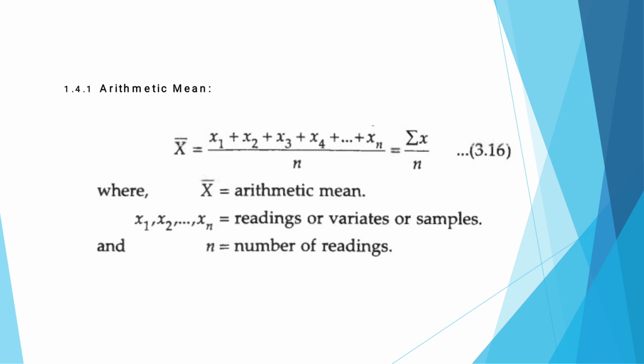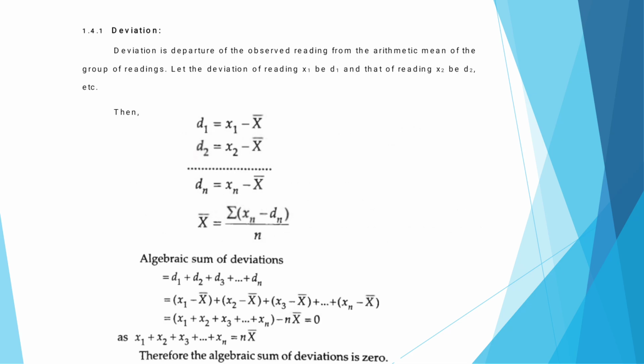So calibration always involves comparing our target instrument against one of three things: a primary standard, a secondary standard with higher accuracy, or an instrument of verified known accuracy. Ultimately, all the working instruments used in daily field measurements must be calibrated against a reference instrument of a higher accuracy grade, ensuring that every measurement can be traced back to a primary standard.